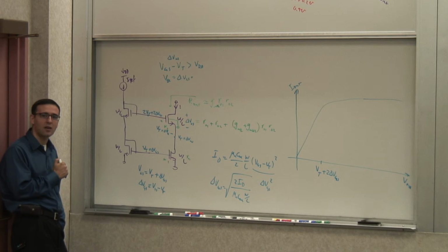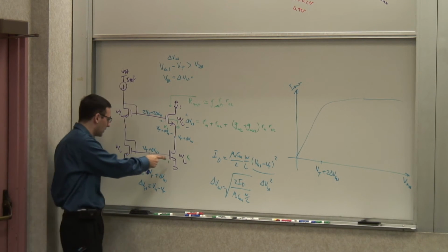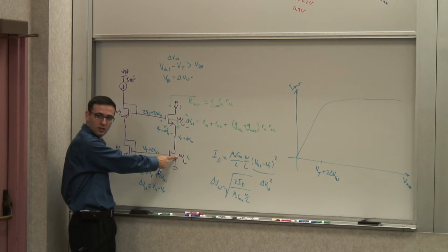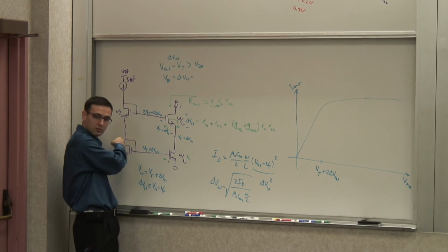transistors is having a lot more drain voltage than it could withstand. One of these transistors could be operated at a much lower drain voltage than it is now, without entering the triode. Which one is it? The far left. This bottom right. So, this one. I can't do much about that.